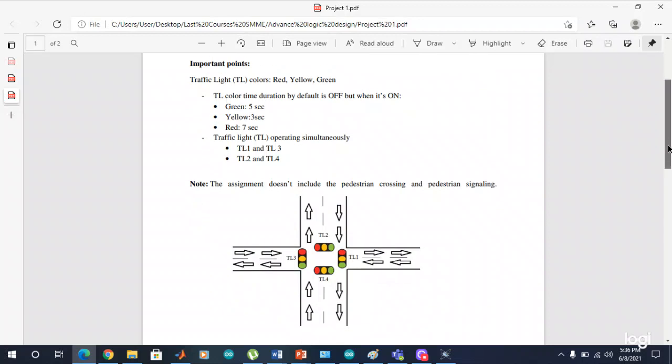These are two basic points you need to keep in mind while coding. I'm telling you this before the schematic because TL3 and TL1 both have the same functionality. So I will connect this red light with this one, and use a single Arduino pin. For example, I will use pin number 0 for this red light, and I will short TL1 with TL3. I'm just giving you an example. Once we do it, you will understand what I'm trying to say.